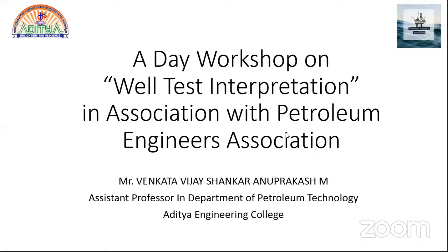Okay, sir. Next question. Which is the best well test type in terms of getting accurate reservoir parameters, in terms of cost and time taken to carry out the test? Okay, very good question. See, anything related to cost: we are shutting the well, so definitely it will cost you some money. Generally we will close it for 3 days, which means 72 hours, 24 hours into 3. So we are wasting money for 3 days for getting very crucial information.